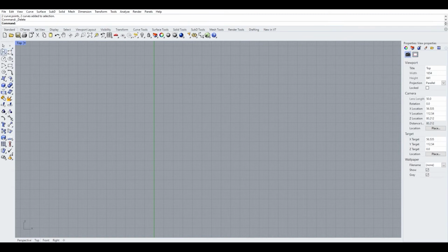I'm going to select that same polyline or that same line tool again. But I'm going to draw your attention up to the command line. This is the first time you're seeing this. The command line here tells you which tool you have active and what your options are for using that tool. It also tells you what you should be doing next. So because I have the tool active, it tells me define the start of the line.